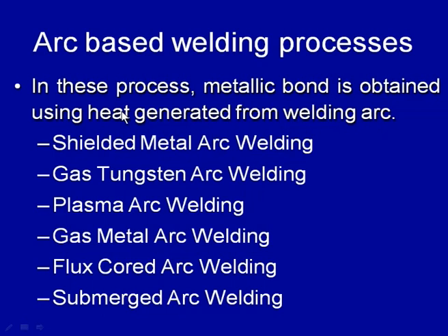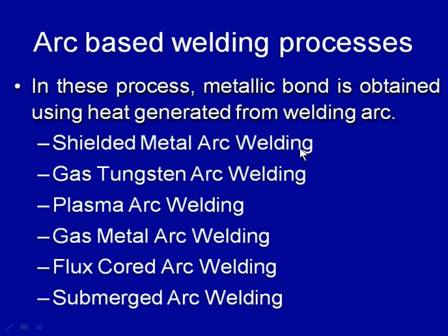In these processes, arc is invariably part of the welding process for generating the heat, and heat generated is used either for melting the faying surfaces or for melting the filler material and the faying surfaces both to get the metallic continuity. For example, in shielded metal arc welding process, the arc is established between the consumable electrode or shielded electrode and